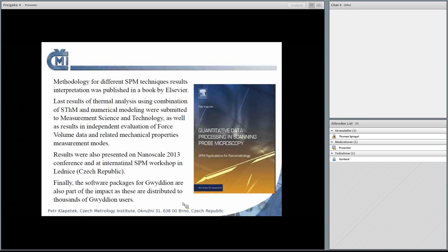As thermoelectric materials or energy harvesters? So for the materials themselves, the goal is to improve their ZT. I didn't show it in the beginning, but if you look at Frank's slide, some of the nanostructured materials have a ZT at least a factor 2 higher than normal materials. And this can open a lot of applications, because if we double the ZT, we can reach applications that are used now by other thermal processes, or mechanical thermal exchange, for example.